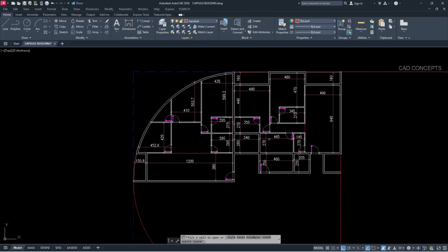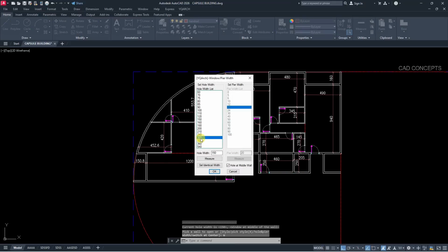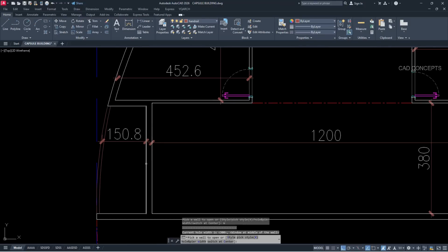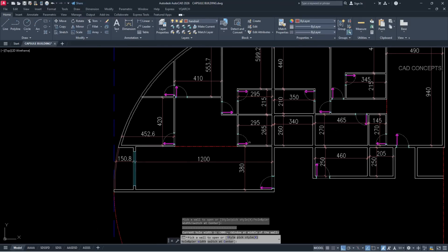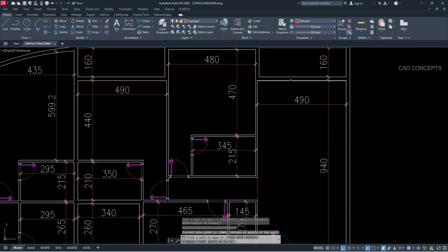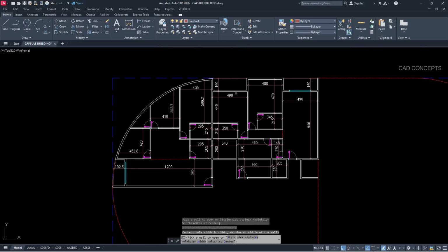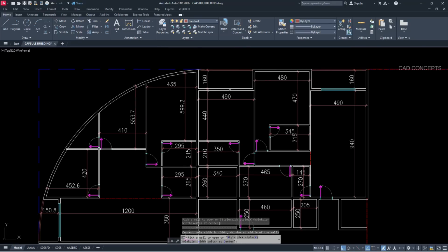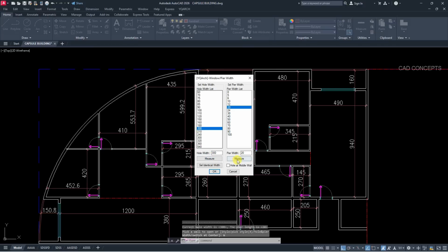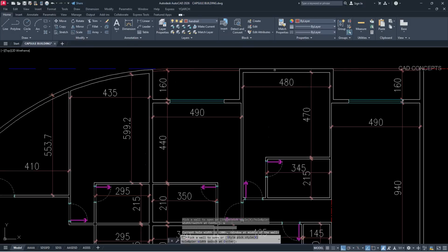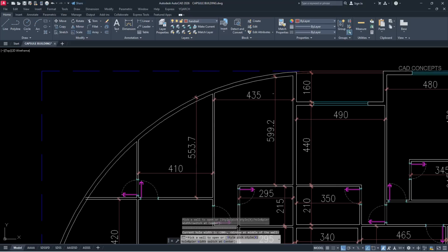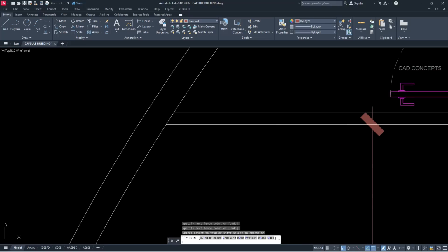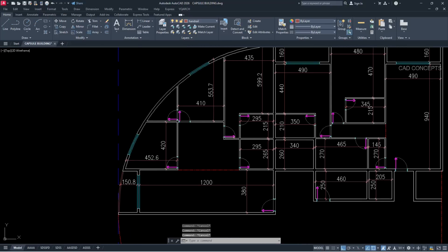We'll provide auto window, type AW, hole and pier width 300 centimeter for sliding door, and click over the wall. 1, 2. Okay, 1 here. 3. 200 centimeter hole at middle wall. Our window, bedroom window. And kitchen also same as it is.